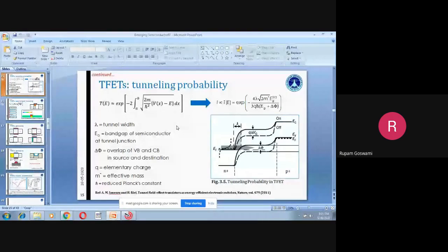So usually it is a very simple fabrication method, and you can also see from the last section where I discussed it, it is very simple when you see it on a macroscopic level. At a macroscopic level, any particular material when connected as a two-terminal element can give you a memristive property. So you can imagine that even if we scale down the dimensions, the fabrication process still remains very convenient as compared to MOSFETs and other devices.